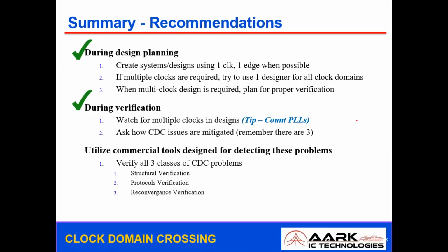Structural verification, protocol verification, and reconvergence verification are the three important steps that you need to adopt during CDC verification. CDC verification is a separate thing, which you can do by looking at a tool like JasperGold. This is the tool we can make use of to identify these issues and address them. This tool is from the Cadence environment. Similarly, other vendors also have different CDC tools.